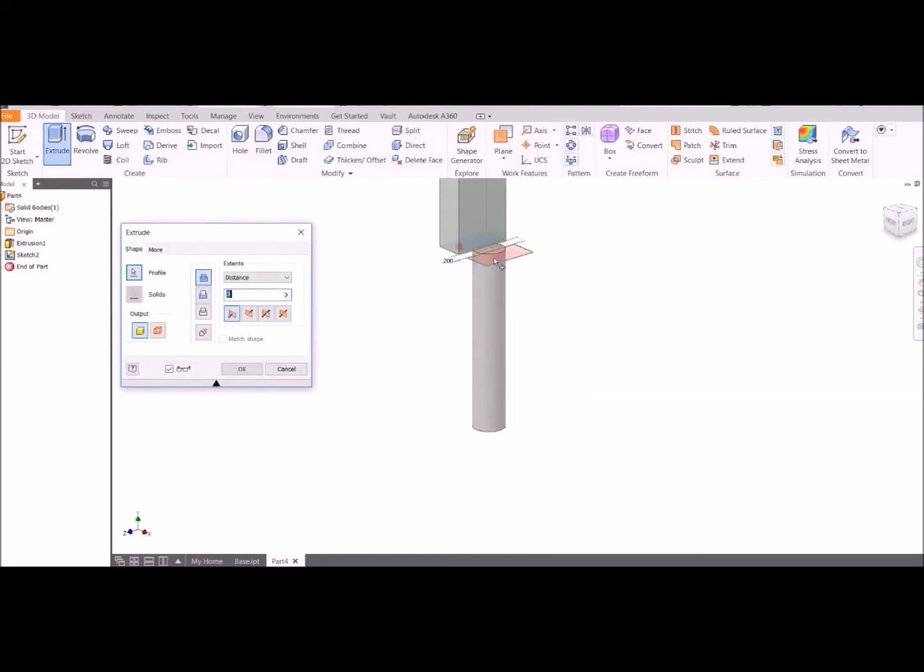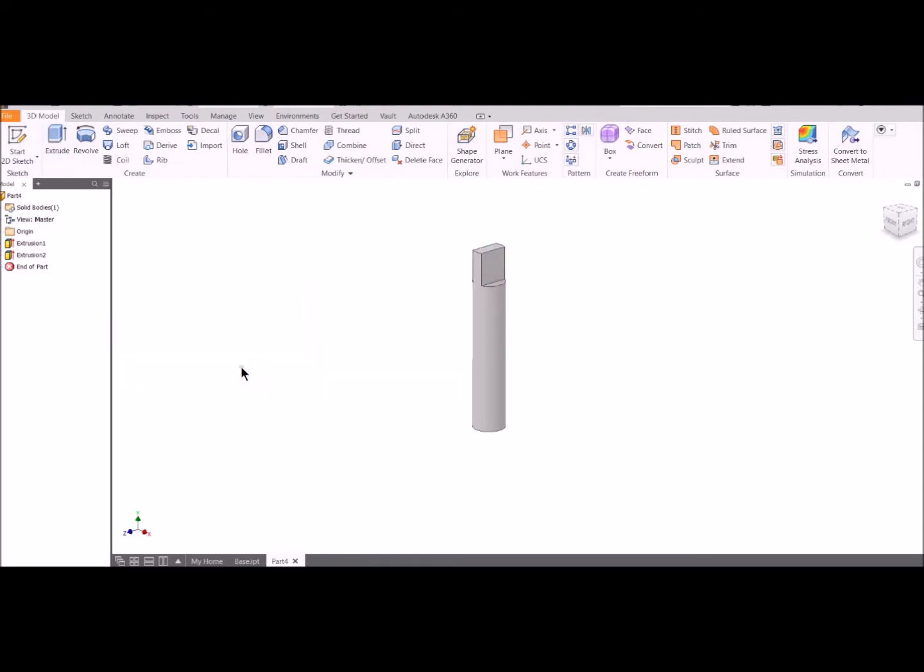So I'm going to extrude this down. Now, we had cut out 1/2 inch. I think I'm going to make this just a little bit longer than 1/2 inch. We don't want it bumping into one another, and you can always go back after we assemble these and modify it a little bit as you see how parts start fitting together here. Okay, so that little tongue is going to fit right up into the frame that we previously made.